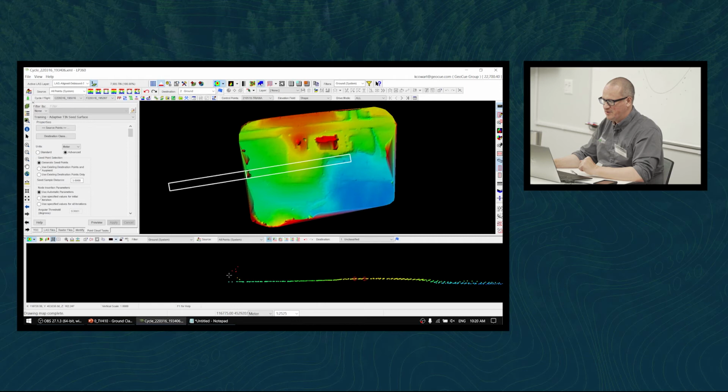So here's some more noise that I need to get rid of. I'll use the large paintbrush tool just to show how that works. See how I've got a paintbrush tool here now? I can just left click and drag around and outline those points and hit left click. The paintbrush tool is a little bit better for doing more precise work. Usually the above and below line tool gets the most work done for less clicks.